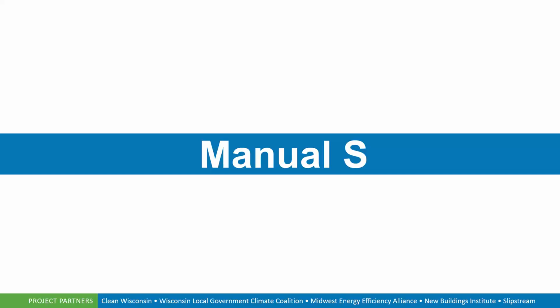We have X amount of BTUs heating we need, an X amount of BTUs or cooling CFMs that we need, and then the total CFM required for the home itself. So one room in the heating mode may require more CFM than it would during a cooling season. So when we look at the documentation, the calculation of total CFM of the home is going to take the higher of those two numbers and then add that in, because our ductwork will need to be sized for it. Say they need 100 CFM of heating into a bedroom, but cooling is only requiring 60 CFM, that could be different duct sizes. So we want to make sure that we have the appropriate size in place.